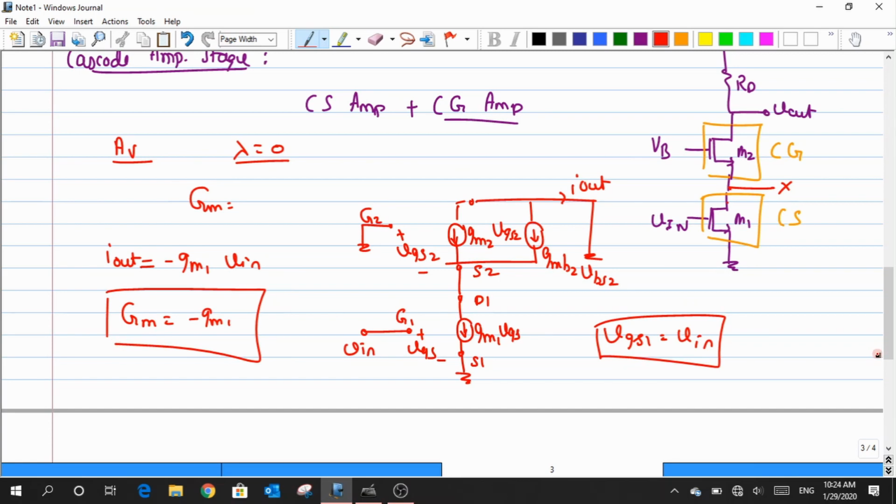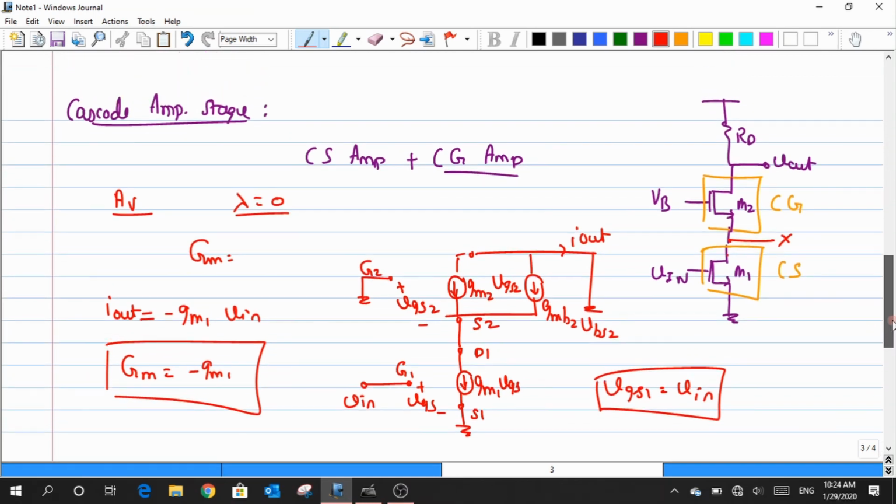Is there any difficulty in computing the value of R out in this case? What is the R out of this? Because that would ultimately give us the gain expression, right? Yeah, but R0 is basically infinity, so we have an output impedance which is just RD, which goes in parallel with an infinite impedance, so it is effectively just RD.